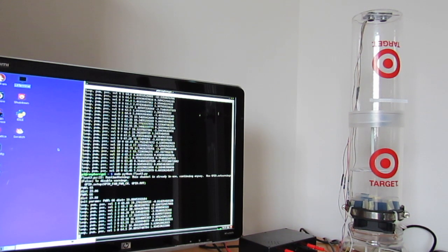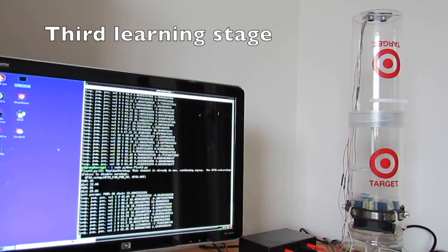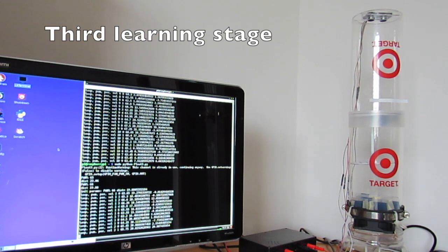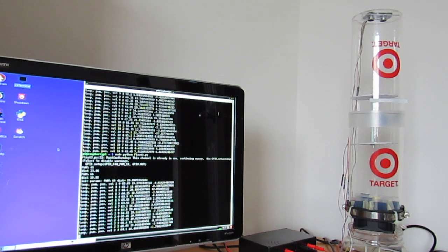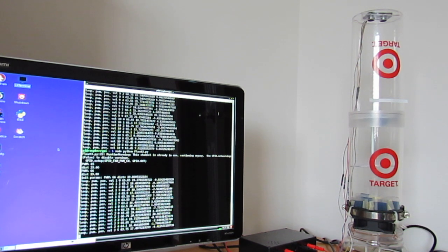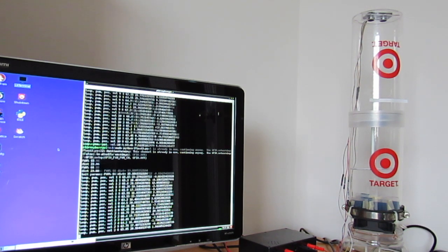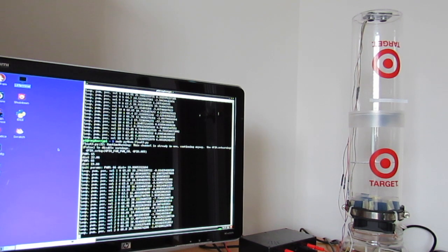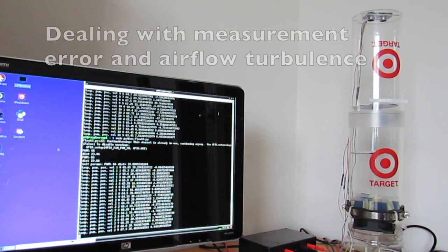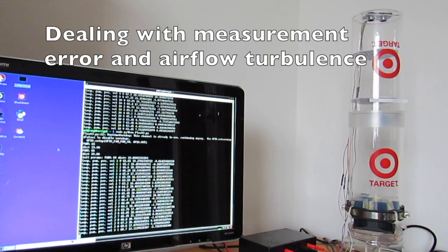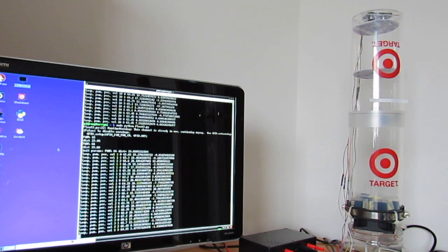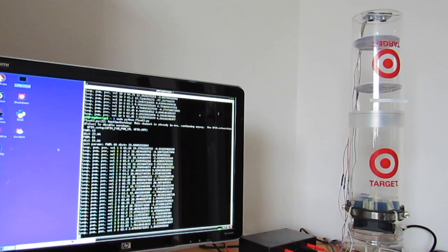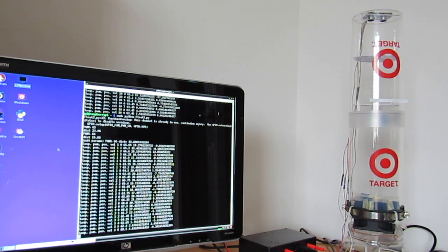Now some people stress that the Raspberry Pi is not recommended for critical real-time control. In this case, I am not sure if it is the Pi or the sensor, but sometimes pulses are lost which cause errors. I accounted for as much of this as I could, but either the Pi missing pulses or sensor error throw the system completely out of whack, at which point you just have to let the system adjust back by itself and learn again.